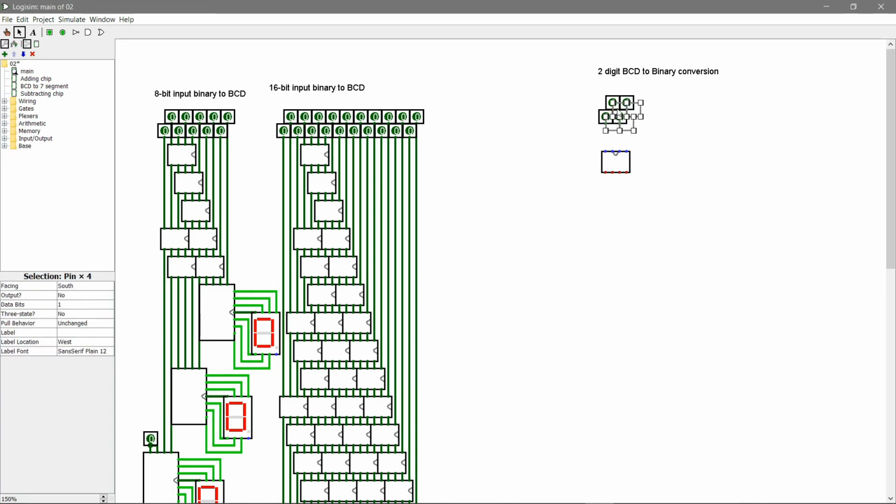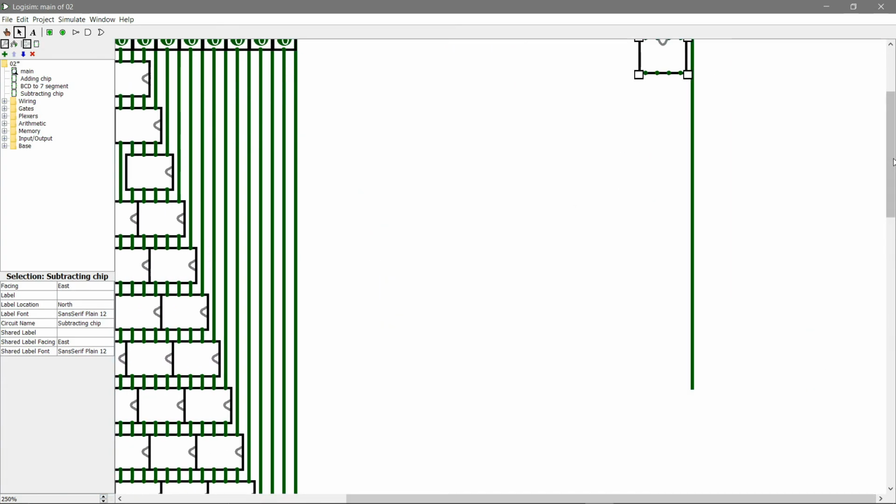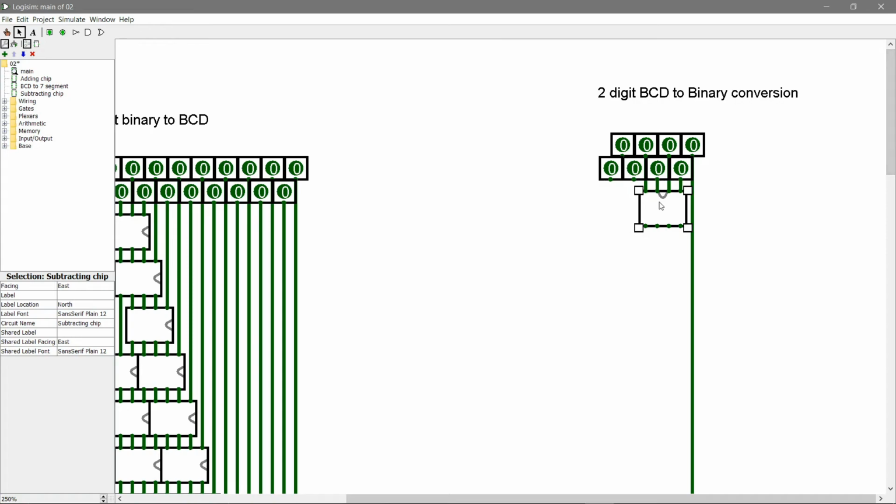So just be careful. Alright, so you have 8 here, and you know this bit doesn't go through any of the tests. And you want to connect them like this. So if you can't see them clearly, let me just magnify that. Alright. This chip represents the comparison at the 1's place. This chip represents the comparison at the 10's place.